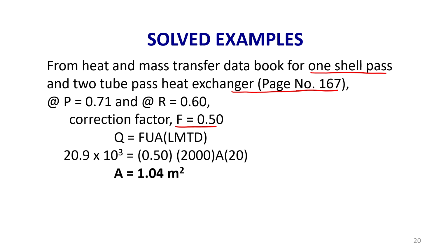Now, the equation will be Q equal to U A LMTD, no change, multiplied by the correction factor F, where F is the correction factor.